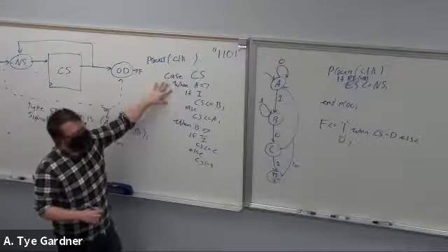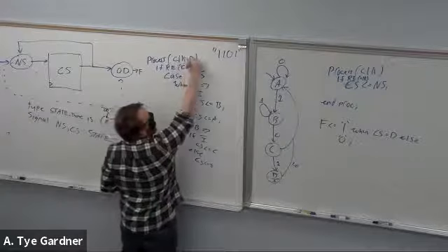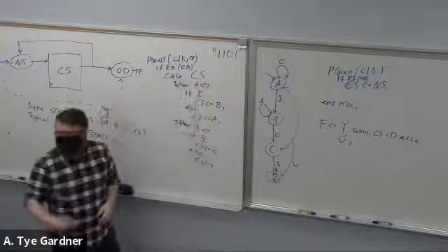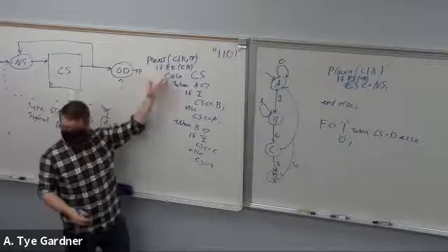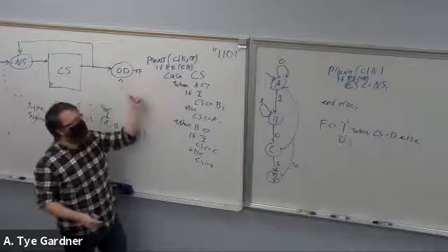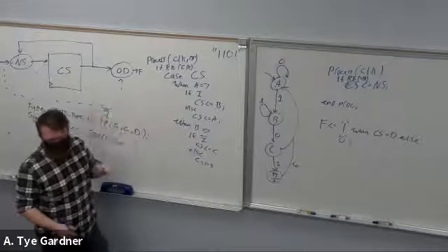We start into state A. And to make sure that happens, we write some sort of, so here I need the if rising edge of clock. But if I want to make sure I start into A, the good way to do that is do the clock and reset, right? And do an asynchronous reset, right? This says if reset equals 1, state equals A, else if rising edge of clock, case, right? That's a good way to make sure you know where you're starting in the state machine.